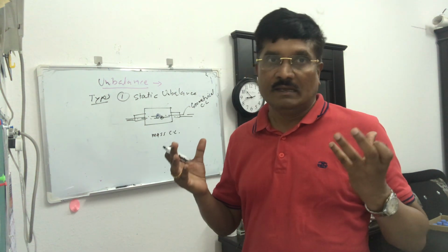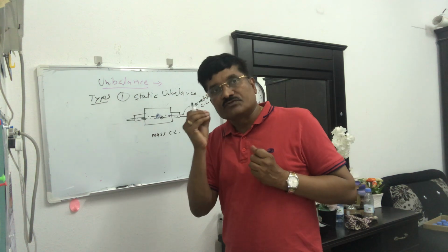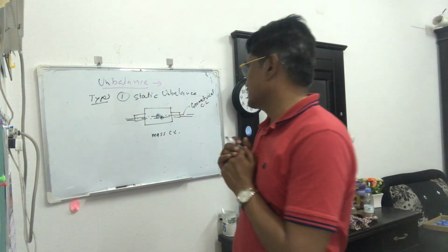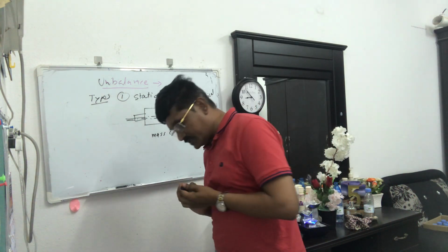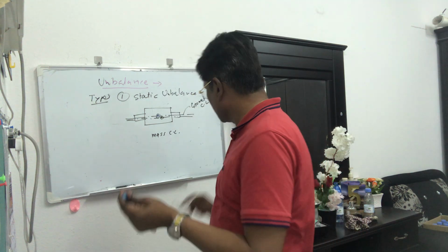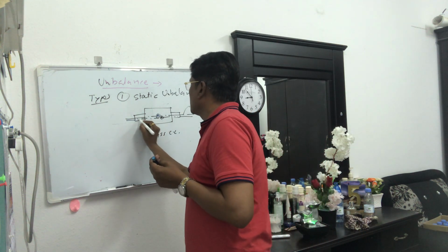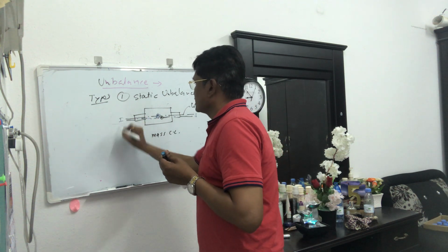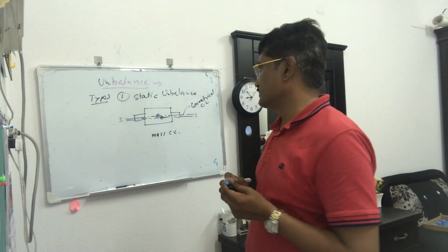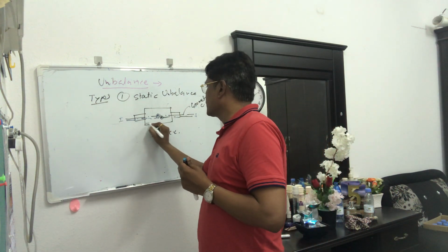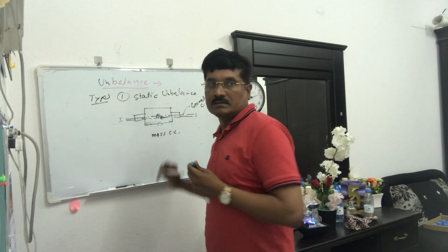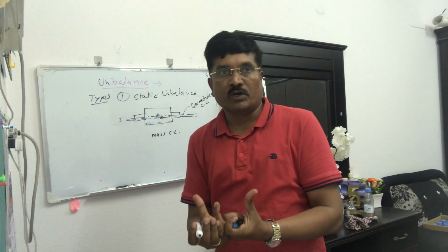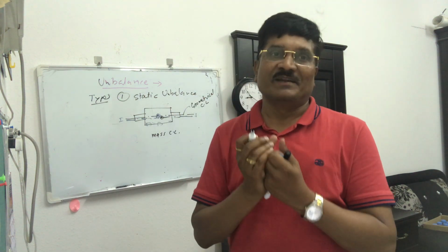Unbalanced force is created, and due to the centrifugal force of that unbalanced weight, it starts vibrating. That is called as the effect of the unbalance. Now, if that mass center line is perfectly shifted parallel to the geometrical center line, then it is called as static unbalance. Means all the weight is at one side, like this. When you rotate the shaft between the bearing, it always stays like high weight is bottom side. That is called as a static unbalance.